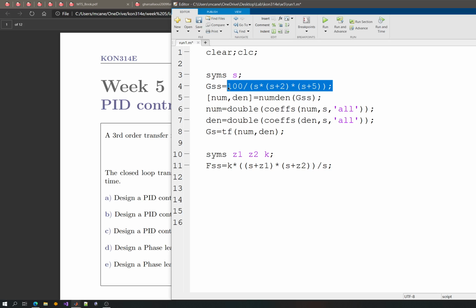So I can choose one of the stable poles because of internal stability and the things I've mentioned before in this lesson. All poles and zeros that are cancelled should be on the left-hand side, and S equals zero doesn't count on the left-hand side because it's neither on the left-hand side nor on the right-hand side. It is exactly in the middle. So this means that that's not a stable pole.